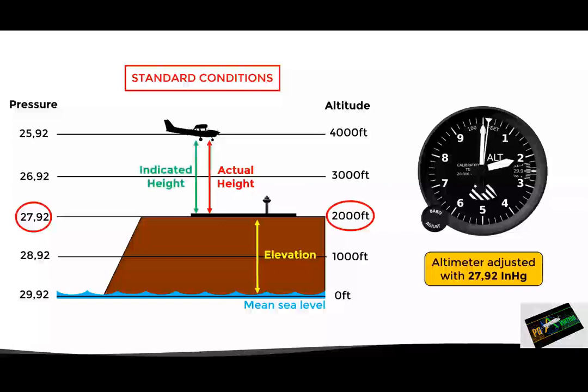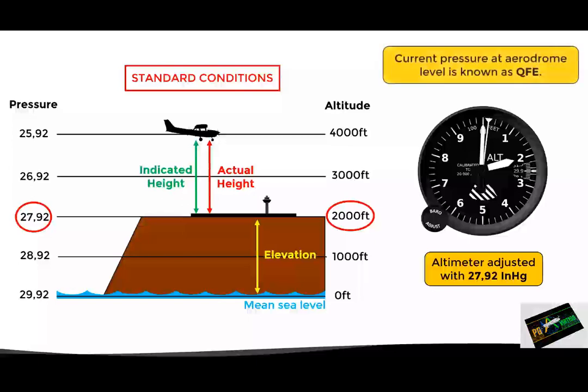In this situation, as we are no longer using the sea level pressure as a reference, the value used to adjust the altimeter is no longer the QNH. It is now the pressure at the airport level, which is known as QFE. Now, as with the QNH, if the pressure conditions are different from the standard, the QFE for a certain airport will vary. Therefore, it is important to obtain updated QFE information if we want to use heights instead of altitudes in our altimeter.